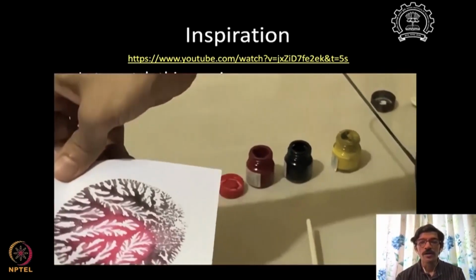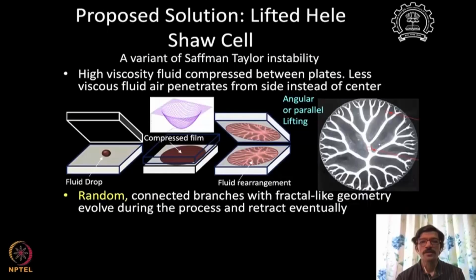Now the idea here is to exploit this process called Saffman-Taylor instability in this cell called the lifted Hele-Shaw cell for fabricating some interesting structures of branched patterns. So you understood the process: you have a fluid drop which is pressed between the two plates, then this is compressed, and then we separate it out. Now instead of doing it manually, we want to do it in a controlled fashion, and for that we now need to design a mechatronic system to carry out that operation.